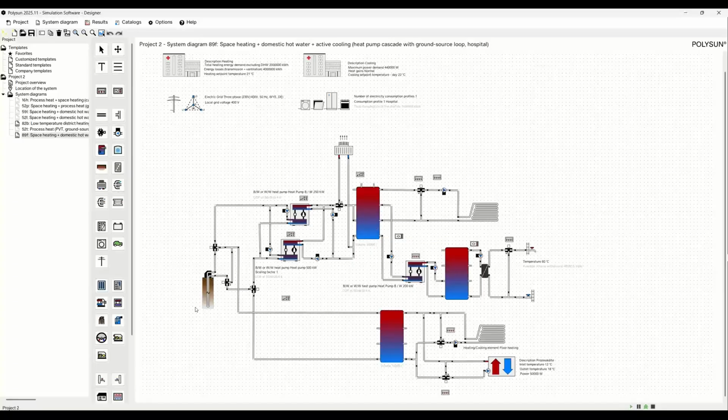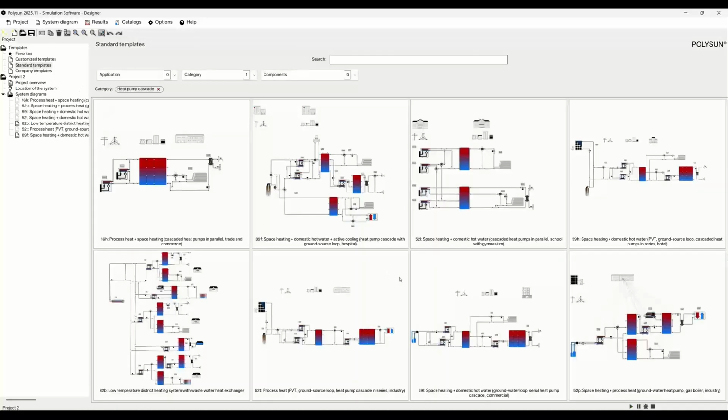So we have a thermal network here that uses the heat where it's used best at the right temperature. So we can use the cooling as a waste heat for the heating, and use this booster to bring it up to another temperature level for hot water. So you can make the combinations here to have the right system.